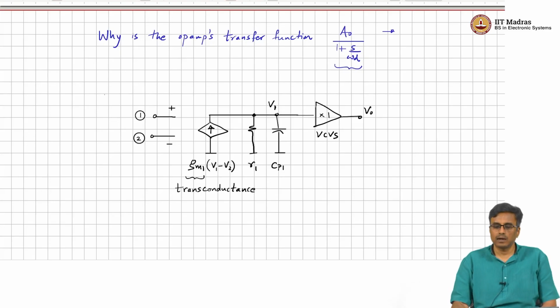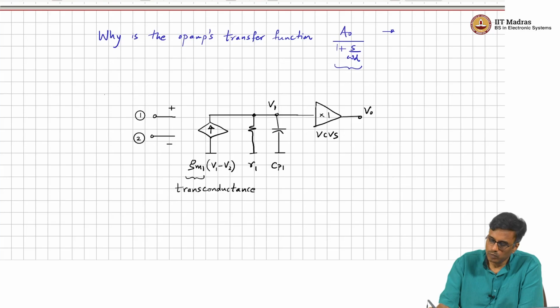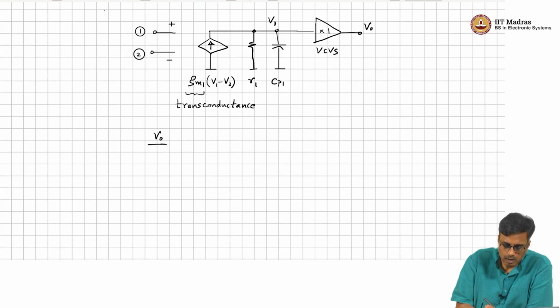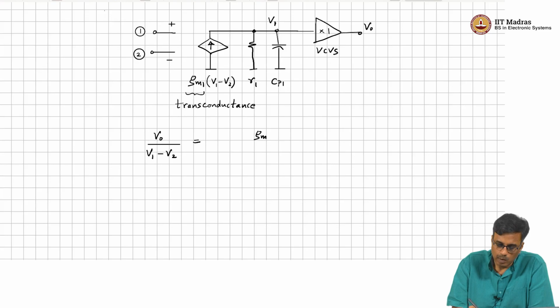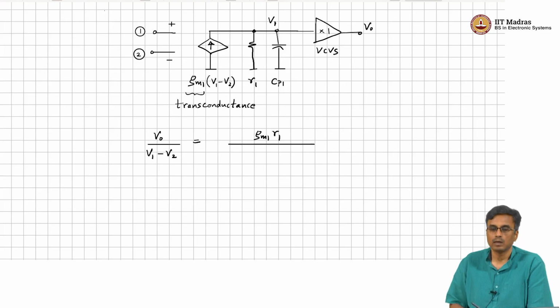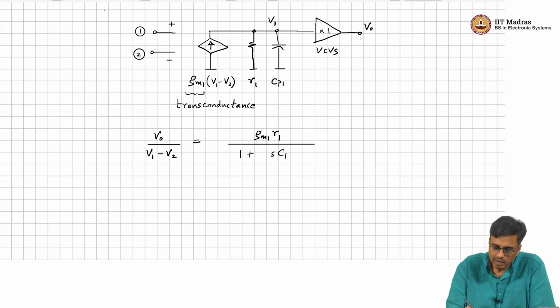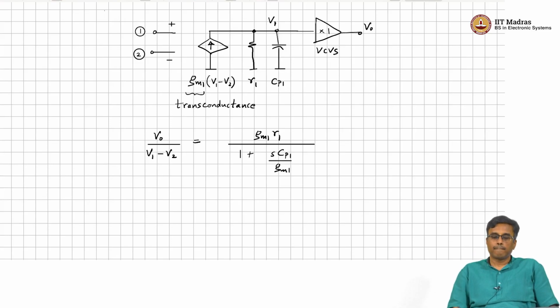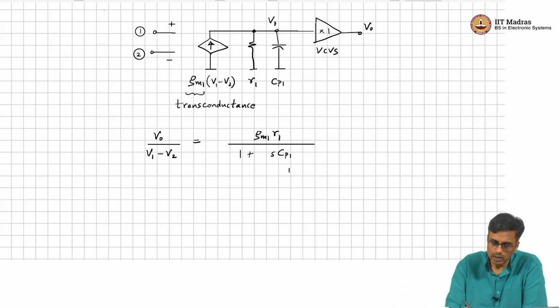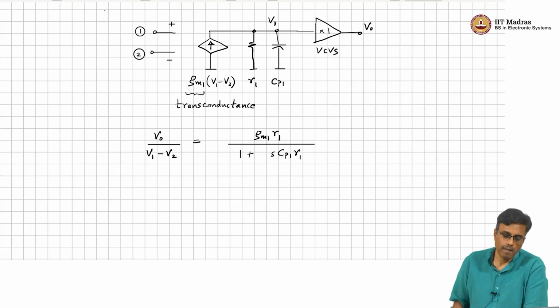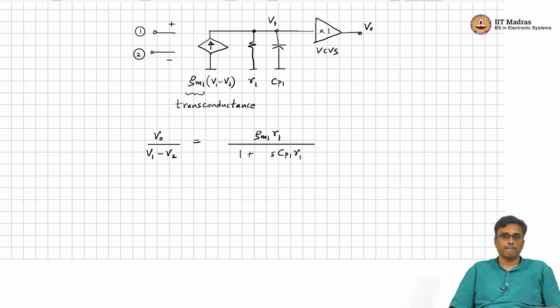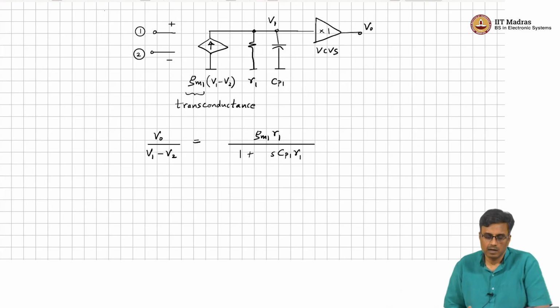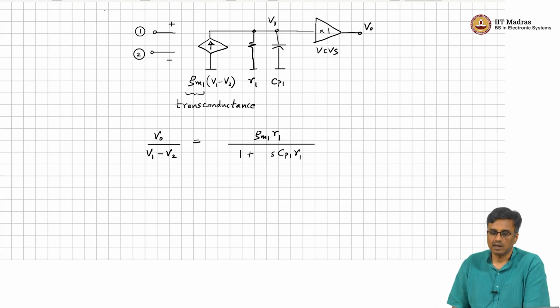So, what is the transfer function we get? VO by V1 minus V2 is nothing but GM1 R1 over 1 plus S CP1 R1. Okay. All right. So, this is an example of...